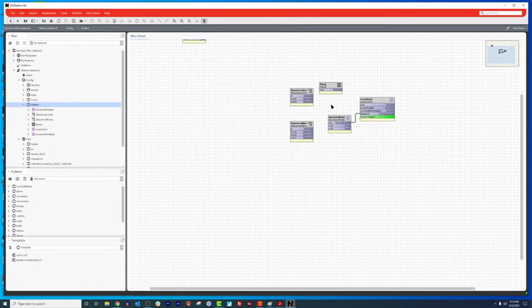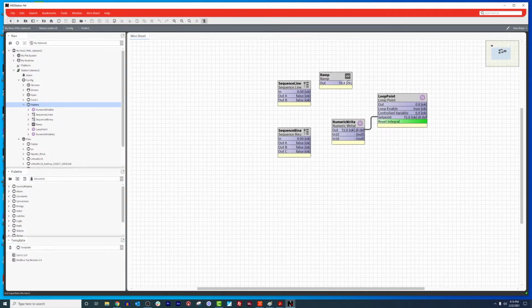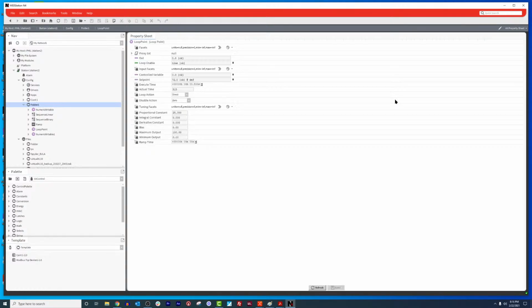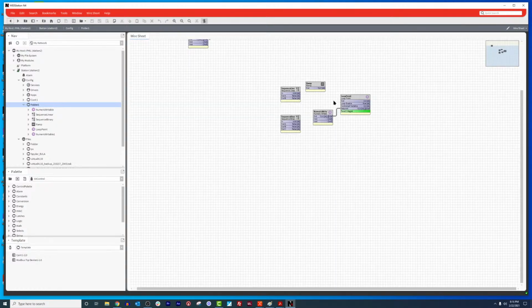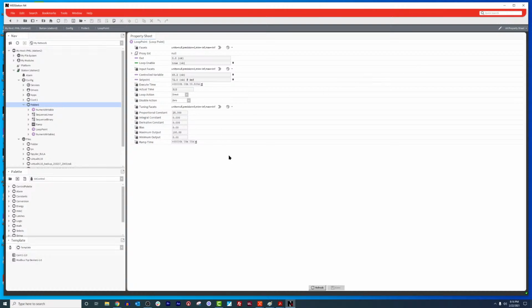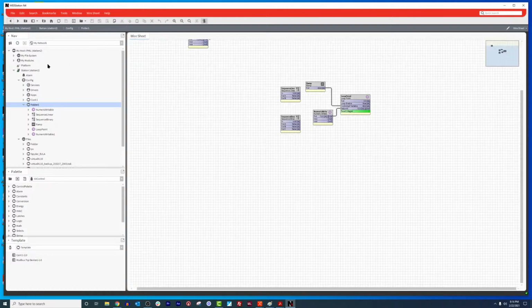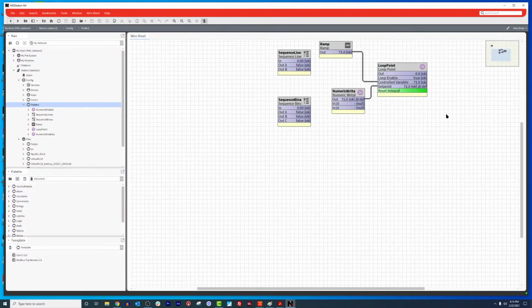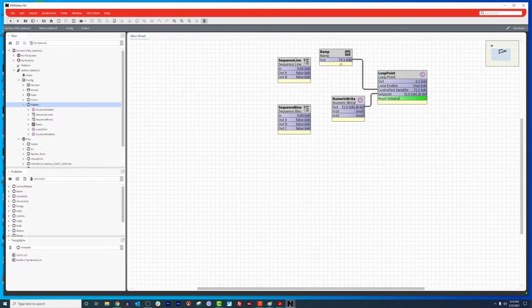So that will simulate my zone temp for this loop. Once I hook this in here, let me make sure I have no I. Okay, I have no I. Good. I'm going to zoom in here again and drag my control variable in here. Is this reverse acting or direct acting? It's direct acting. Good. And so it starts to creep up, and we see the direct response happening right here. You see that direct proportional response, and it's following through.